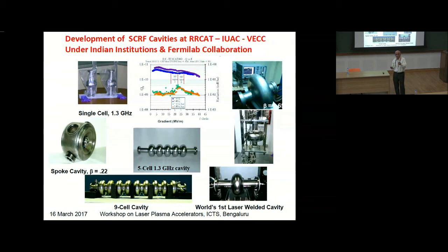The air has to be filtered in such a way that in a cubic meter volume you have not more than 10 particles. So this is called a clean room of size 10, that is, 10 particles per cubic meter. Normally, in a room like this, the number of particles in a cubic centimeter would be several million. So you have to reduce that.